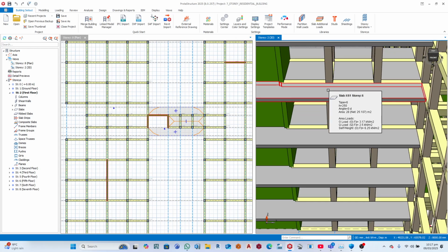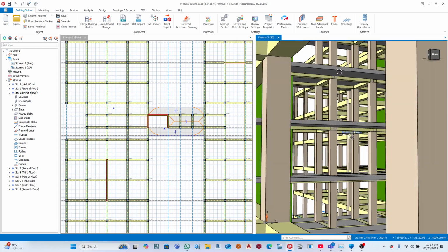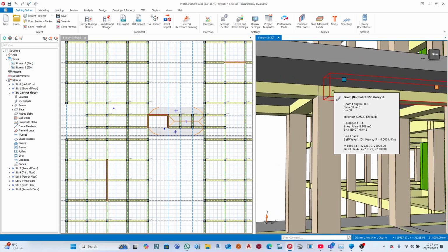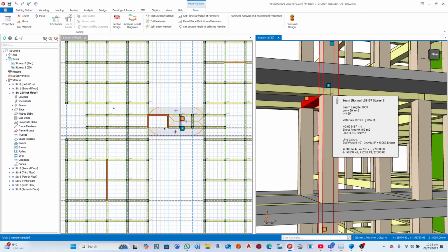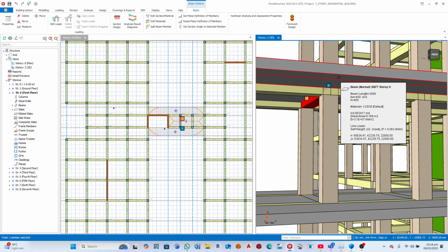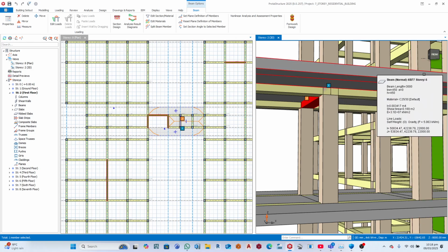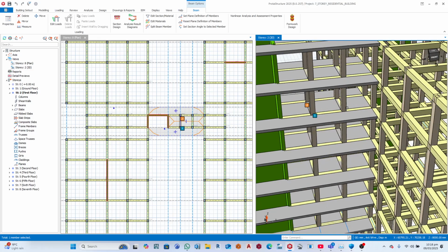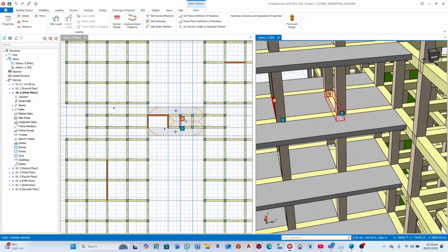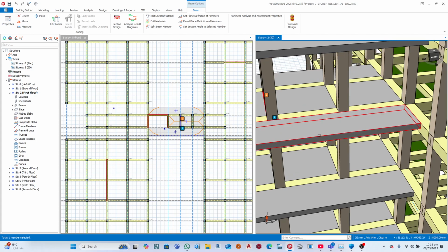So if we wanted to be industrious, we would actually extend these beams and bring them out to flush with here, so that they become like overhang beams. This beam will be continuous this way and that way, so that they provide strength to this. But even just like this as a slab, if reinforcement is going all the way up to there, it will be stiff and it will hold. Yeah.